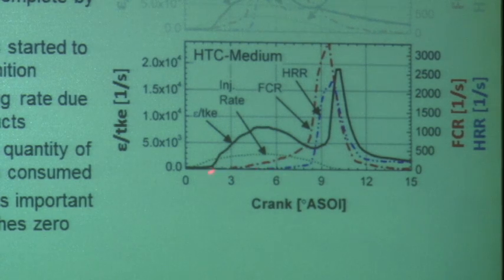And during that process, you can still see there is evidence that the turbulence that was generated by the jet is quite high, but it's actually ending over here because the injection is ramping down. So the effect of turbulence is becoming less and less important toward the end of the injection. And yet, right here is where we see the ignition occurring. So you can see that the ignition is really a chemical process, dominated by chemistry effects, because the turbulence is ramping down.